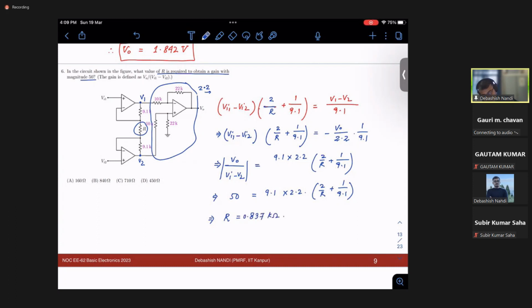So the same analysis, you do it in the same way. Consider the output difference stage first because you know how to solve that. And then you come back to the input stage. Use KCL at this node, or you may use it at this node and this node also. And then you find out by simply adding and subtracting this circuit. Remember that this is a difference amplifier, so you have to anyhow make it a difference of two terms. That is the manipulation of algebra only, how you solve these circuits. So this should not be any problem. This is as far as question number 6.